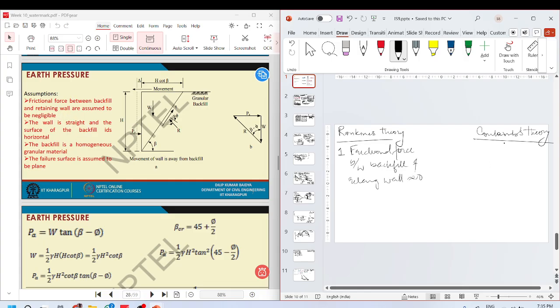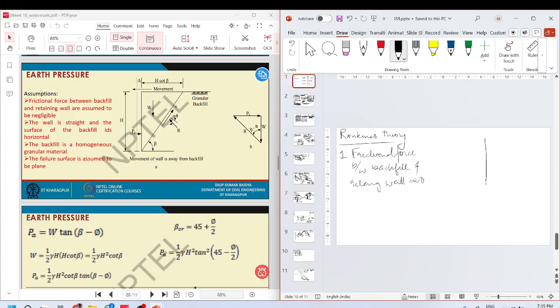What this actually means is that when you make this kind of a free body diagram, if this is the failure angle and you have an internal friction angle of phi and you have this weight here and you have a passive earth pressure acting in this direction, the resultant of these will form an angle of phi with the normal.